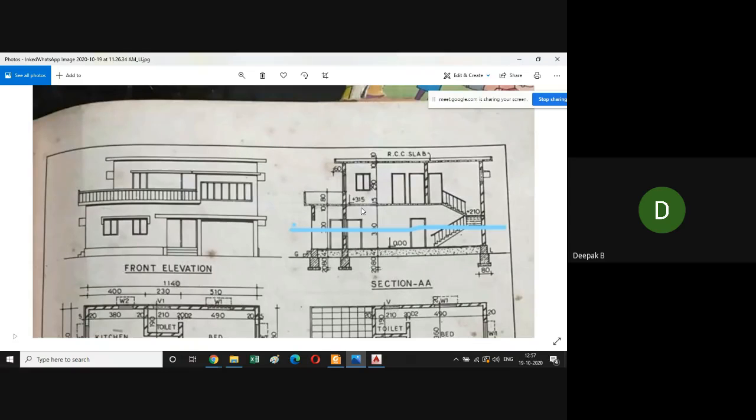Even ground floor undulations will be there. If it is sloping ground, we can easily show that at one point it has a reduced level of 0.00. If it is sloping down, you can just mark it as -5.000 in terms of meter. So that is what it is used for. It's just showing the level, elevation level. Okay, anything else? Anything else?